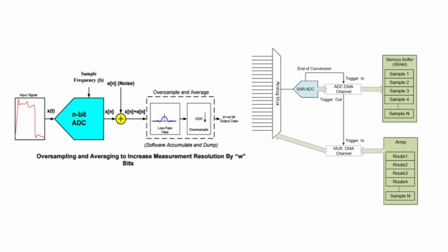Another popular one is an exponential filter, sometimes called an IIR, infinite impulse response filter. This calculates the new output based on a weighted average of the new incoming sample and the previous filtered output. It looks something like new output = alpha * new sample + (1 - alpha) * old output. That alpha value acts like a speed or smoothness control. A smaller alpha gives more smoothing but slower response. More advanced options too, I assume. Well, yeah. For more specific noise problems, engineers might use more complex filters like FIR, finite impulse response, or CIC, cascaded integrator-comb filters, especially in digital signal processing applications, to reject specific frequency bands of noise.